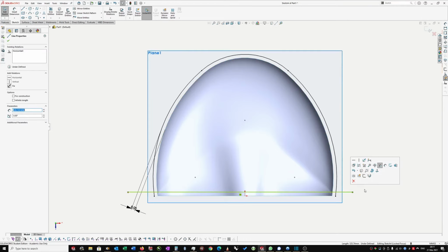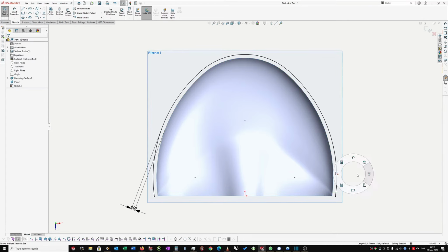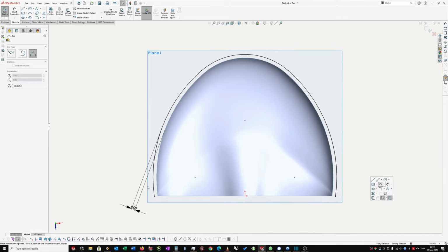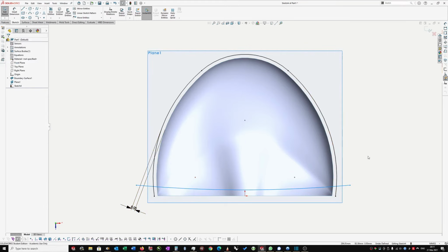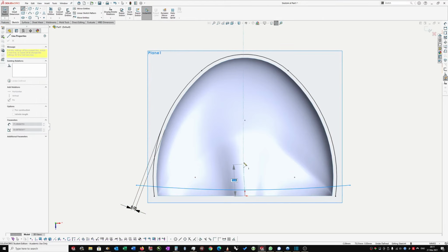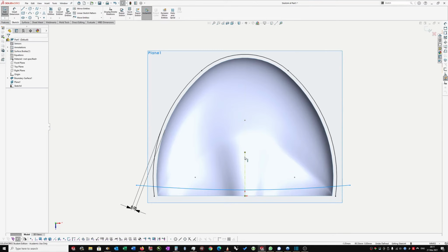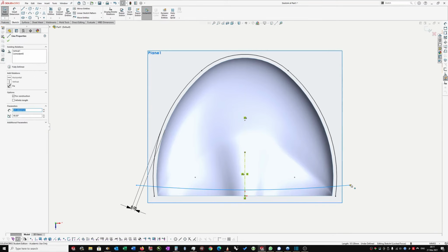I'm going to make my life a bit more difficult and show you how to use a curve instead. So a 3-point curve, something like that, and then my usual establish relationships straight away. I think this should become a habit with you. Just as you go, establish relationships. So I want a center line. I want to make sure that those two are symmetrical.